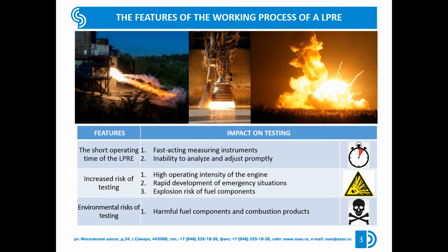Their use causes high temperatures in the combustion chamber and a rapid development of defects which can lead to an explosion. In addition, some rocket fuels are highly toxic, for example hydrazine and its compounds, and tend to explode under various influences, hydrogen peroxide. The danger increases with high thrusts. During tests, the possibility of an explosion, the power of which may exceed the engine's capacity, cannot be avoided.